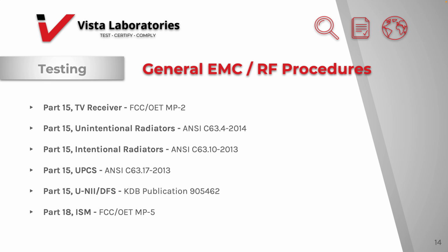Part 15C for intentional radiators follows C63.10, procedures for compliance testing of unlicensed wireless devices. For unlicensed personal communications services, or UPCS, it's C63.17, the methods of measurements of the electromagnetic and operational compatibility of UPCS devices.